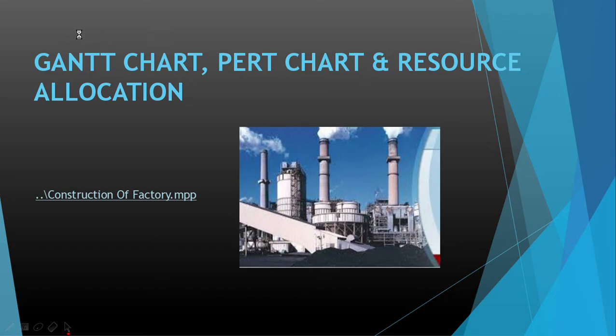Now let us see the network diagram. This is the network diagram for the entire project. We can see the work breakdown structure and these are the broad headings of the work breakdown structure. The enabling work starts with purchase of land and registry licensing, which is followed by temporary connection of electricity and boring. Now we see foundation in the next line, which is parallel to excavation and steel erection, as foundation comes under excavation and steel erection.